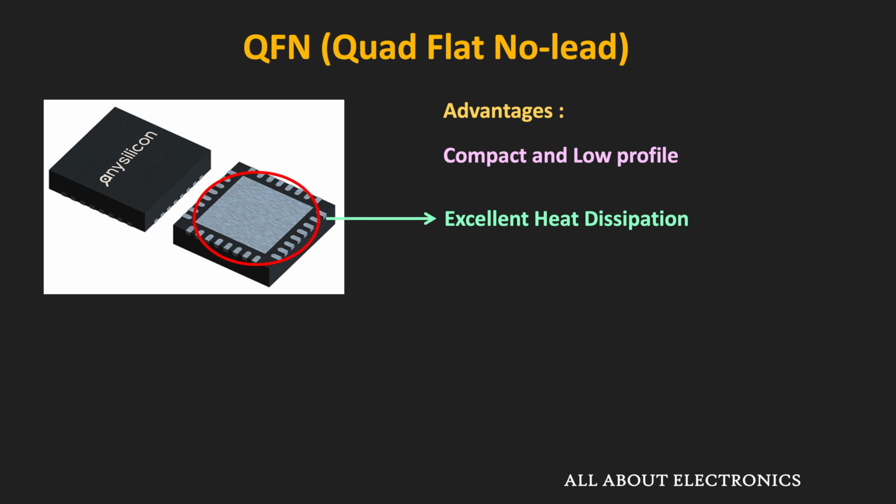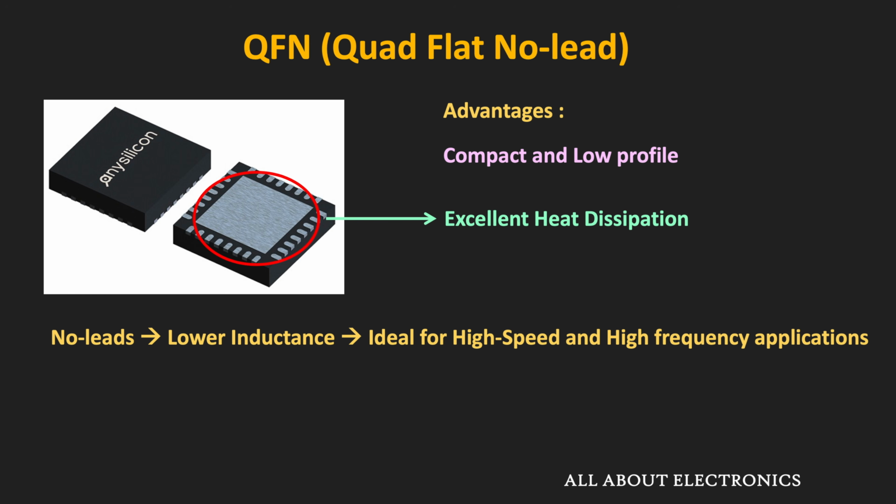Moreover, as this package does not have any leads, the contact pads on this package offer lower inductance. And due to that, this package is ideal for high frequency and high speed applications. Moreover, being a surface mount package, this package is also suitable for automatic assembling of the components. So these are a few advantages of this QFN package.